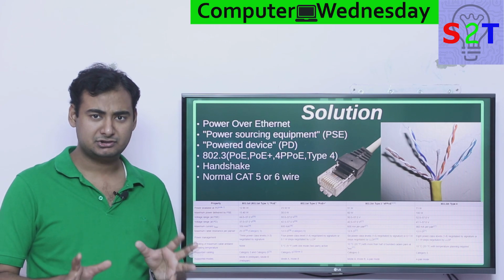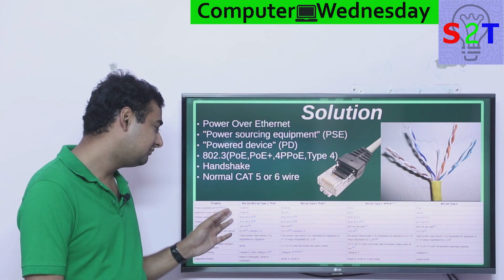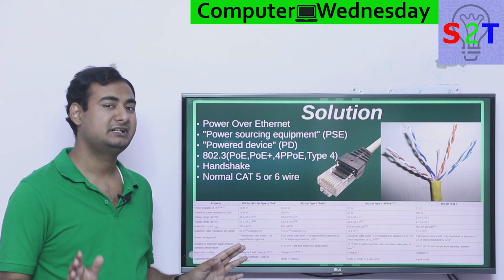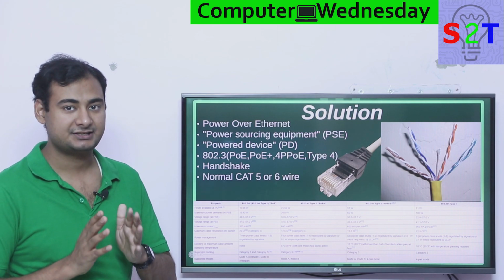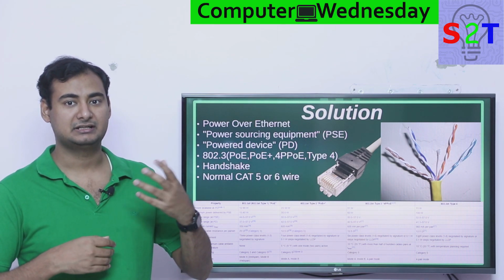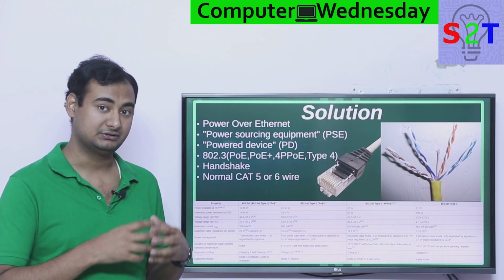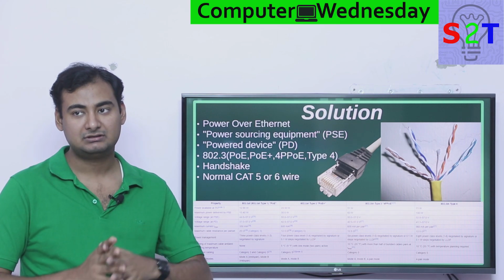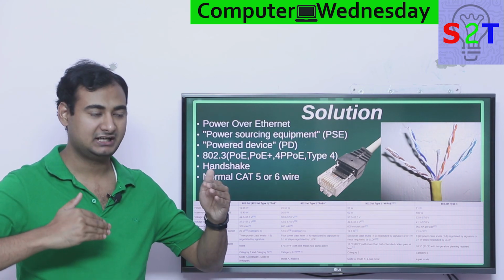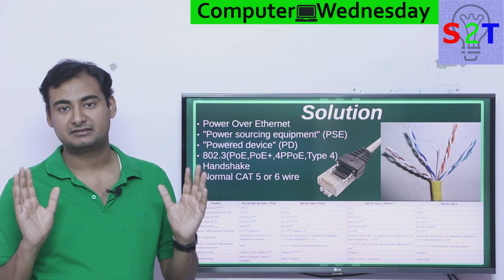Now, to give you a rough context of these things, you have the first standard, the PoE, the original standard. It was barely capable of giving 12 watts, 10 watts maximum. Every piece of equipment was designed to make sure it works under 10 watts. Let's say a phone, when it's ringing, it consumes a lot of power because it's running a loudspeaker. So in that time, it will consume upwards of 12 to 15 watts, but generally they made sure that it works under 10. You never want to be maxing out to 100%. So let's say PoE, just think of it as a 10 watt system.